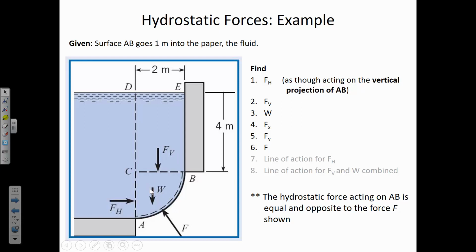Is that force acting on the centroid of that square surface? Good question. So you're asking where is that force located? It's not acting on the centroid. It's going to be lower than the centroid. And it's not actually acting on the projection. It's acting on the curved gate. We calculate the location and the magnitude of the force by considering the projection, but the projection is just an imaginary thing. It's not actually there in the water. But this process allows us to calculate the magnitude and the location by assuming the projection is there. Thanks for asking. That's a great question.